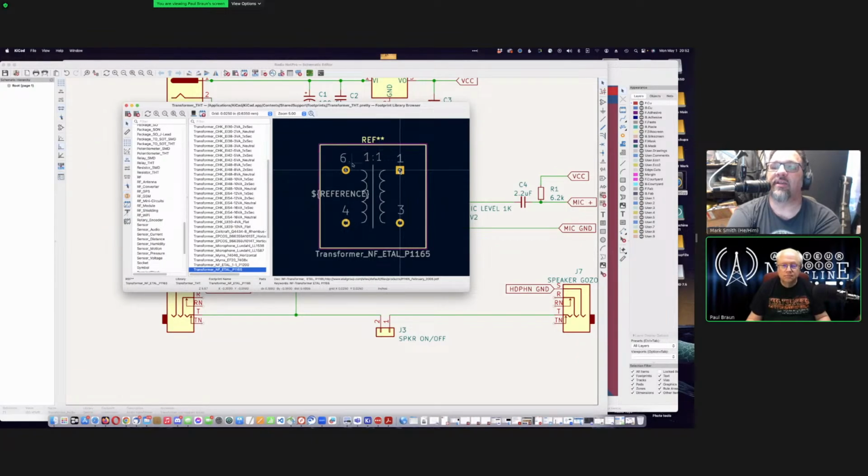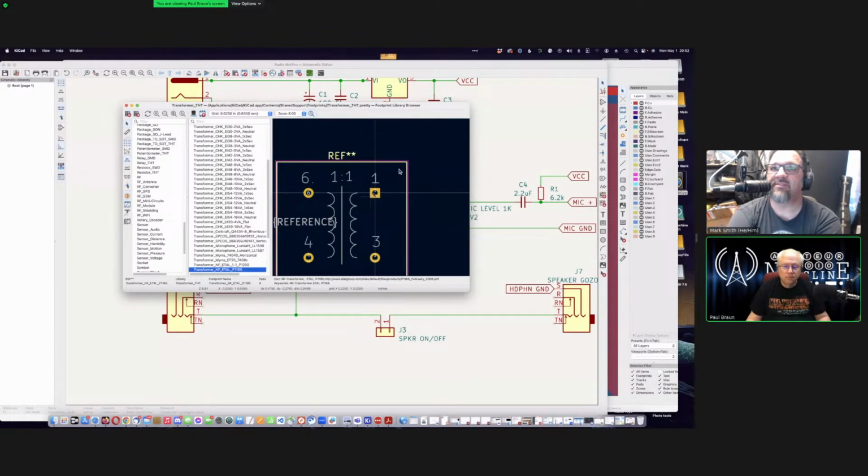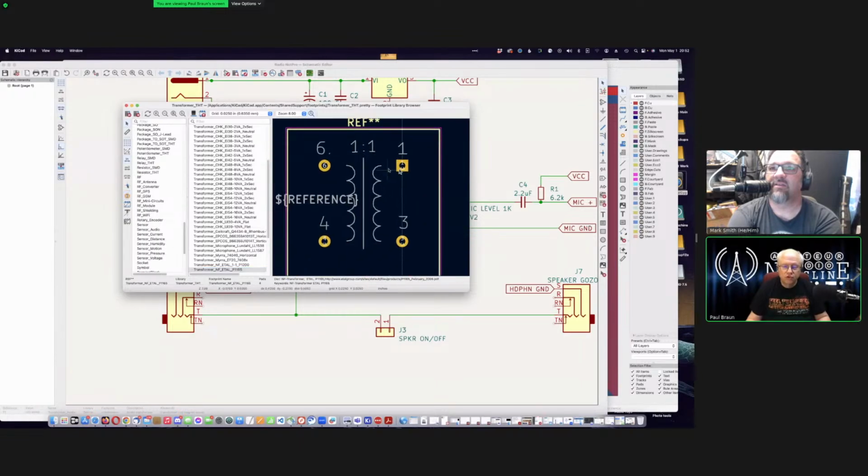So hover over 1 and hover over the origin and hit space. Okay. Why are the DXDY numbers not changing? You hit space? I did. Try again. All right. Forget it. The X and Y numbers are what I should be looking at. Okay. I'm just used to having to reset that. Okay, hover over 4. That's 4.4 and 0.4 inches. Damn it. So the dimensions we're looking for are 0.4 and 0.2 inches.